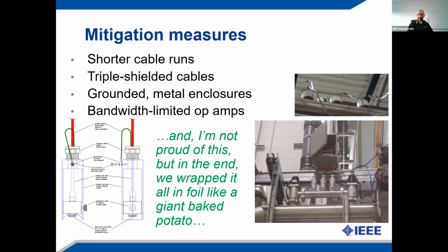I'm not trying to get into too much of the detail, but you can understand this is a pretty major shielding effort. We also did a lot of shielding on the machine side, adding beryllium copper, spring-loaded copper gaskets and things on all the components that were removable on the machine, and used aluminum tape and other things to patch up anywhere where e-fields might be escaping from the machine.